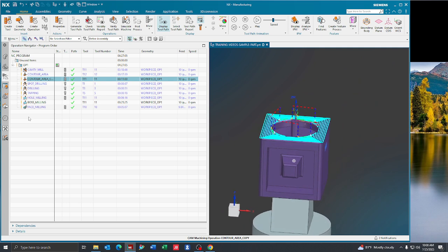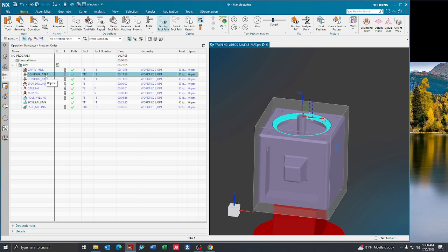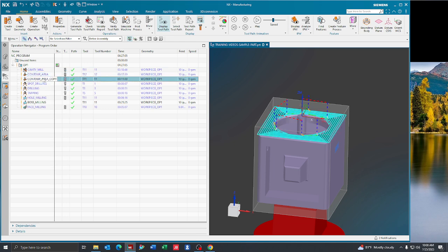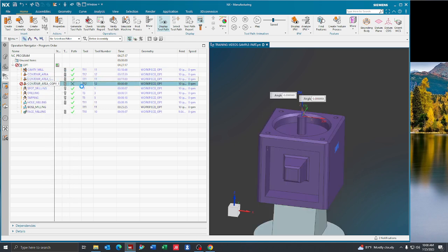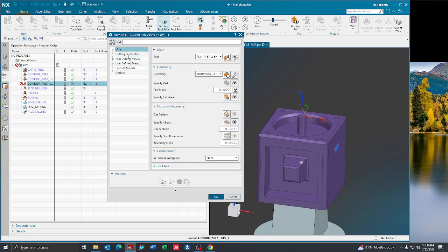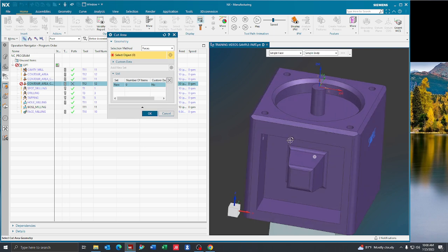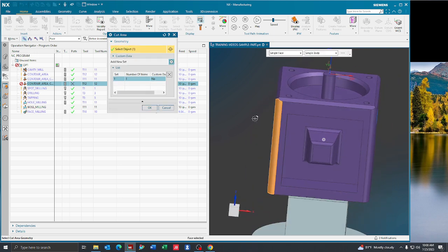The third option for using a contour area is it can be used multi-axisly, even though it is just a 3D toolpath. If you copy it again, we can paste it, and we'll go back to using our quarter ball end mill to surface a chamfer. We can take this toolpath and we can select one of these side edges right here.